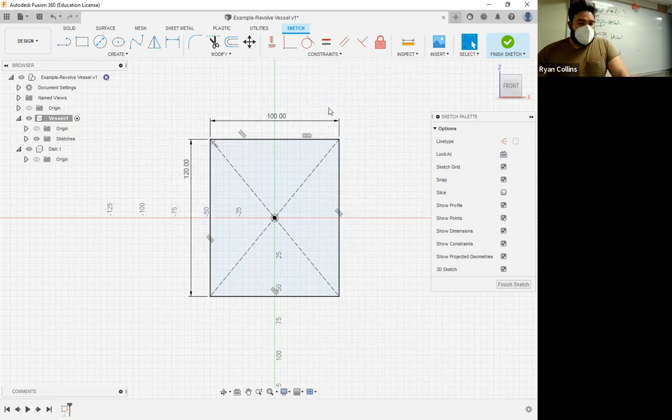Now, the other thing is, okay, this is an actual full sketch. I want this as a reference image, or rather reference lines. So what I'm going to do is double click here and either go over to your toolbox or press X on here, line type, construction line. I click that and it translates that to a dotted line. Hit escape. Now these are not full sketches. See, inside the sketch, it is no longer highlighted in light blue. So these are just reference lines.